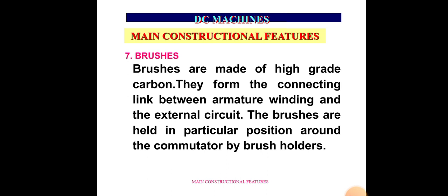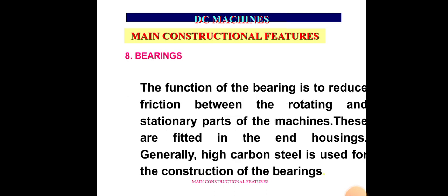The brushes are housed in brush holders and mounted over brush holder sets. The brushes are held in particular positions around the commutator by brush holders. The brush holder sets are insulated from the brush yoke by insulation sleeves.